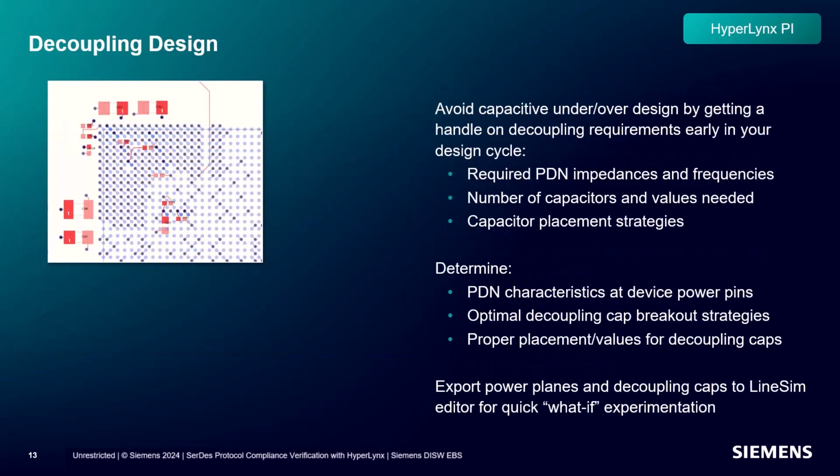Device switching behavior creates AC power supply noise on the system's power rails. When the VRM uses a remote sense line, DC drop at the component input is kept to minimal levels, and DC and AC analysis can be considered separately. When the VRM does not have a sense line, the AC power supply noise is superimposed on any voltage drop that may already exist, and the effects of both AC and DC behavior should be considered together.